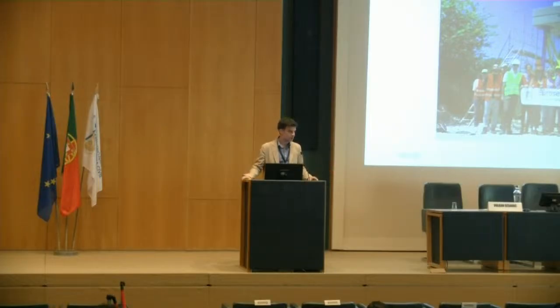A few years ago, we showed that when we excite the structure, even with high forces, like 20, 30 kilonewton, we do not record anything outside of a radius of 2 to 3 times the foundation width. We see nothing with high accuracy, high resolution instruments. This is why it is even more difficult to record something like that within the soil.